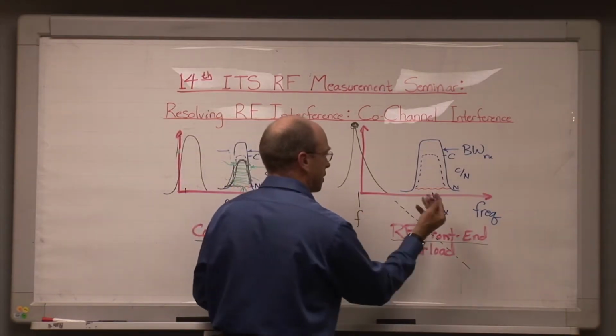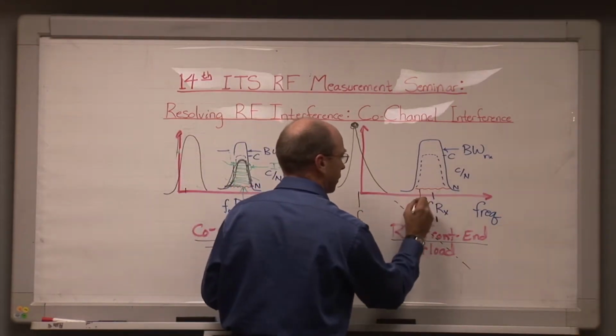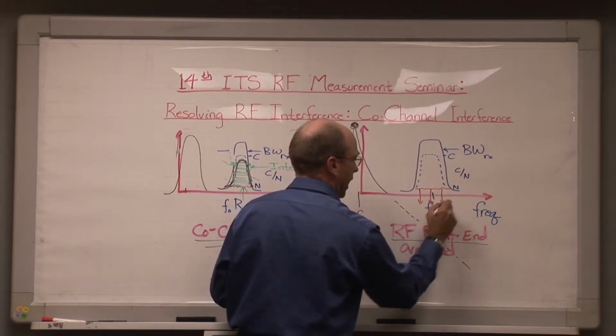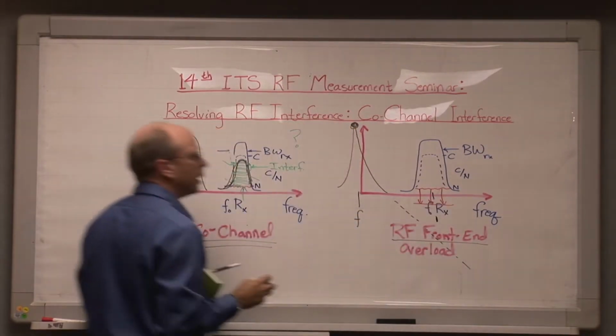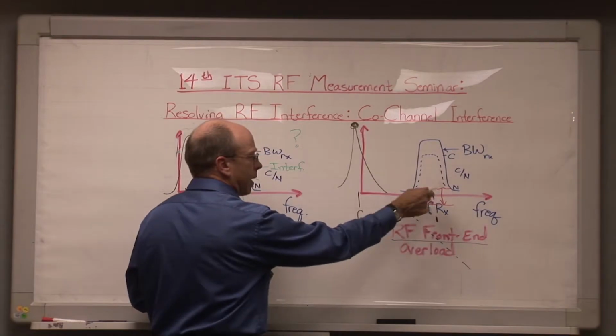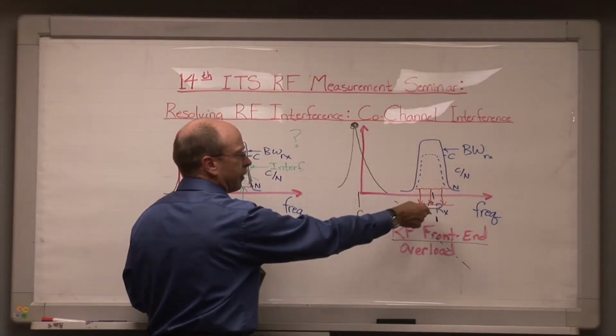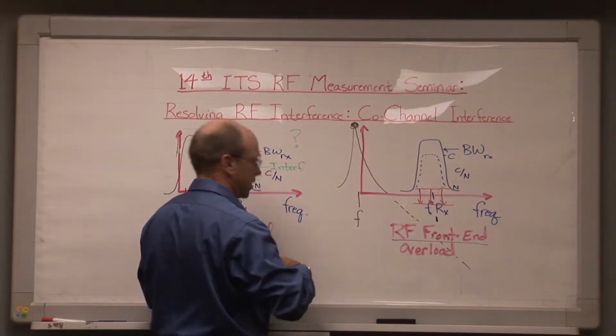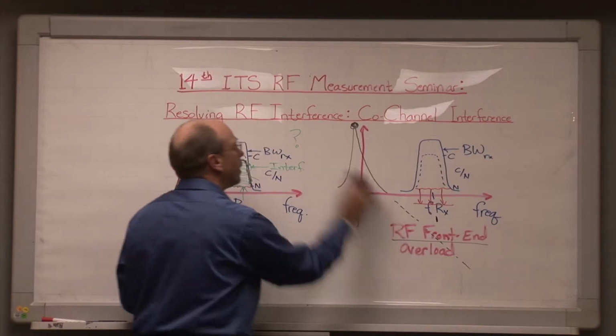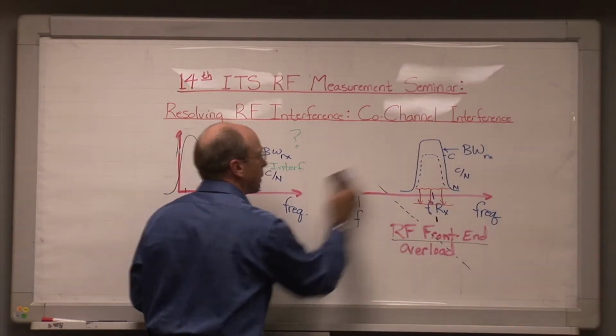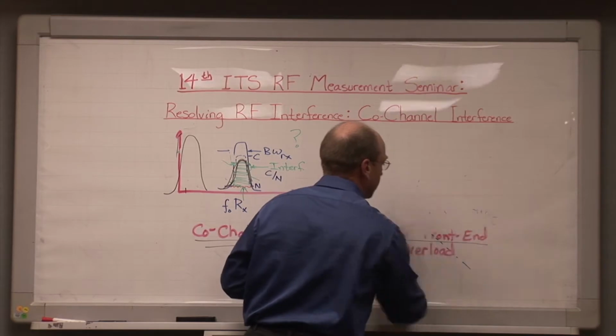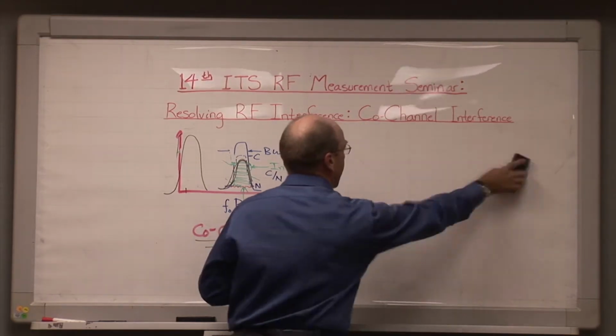Specifically, it'll cause this noise floor to actually drop like that, and it's not actually the noise here that's going down, it's actually the gain of the front-end amplifier, and that is a whole separate problem, which, as I say, we'll take up in the second talk next time. That's just a preview. And then we have, as I said, a sort of a zoo category.